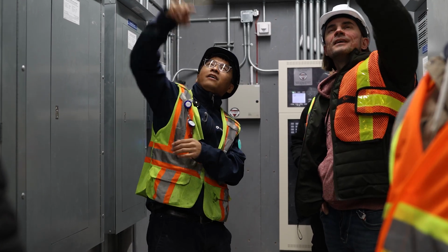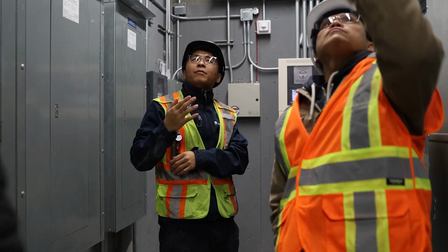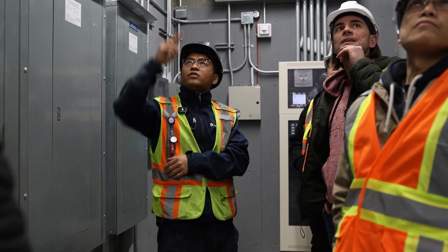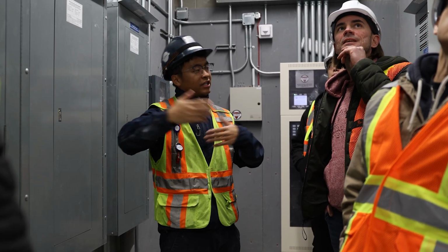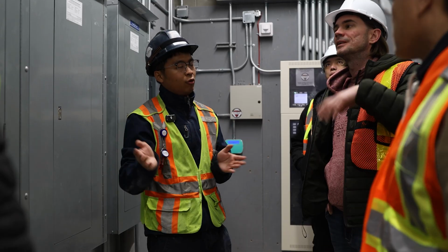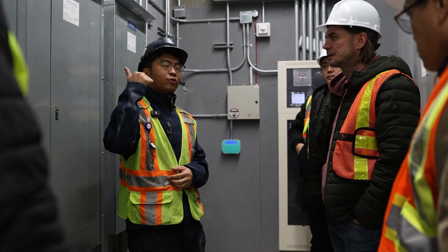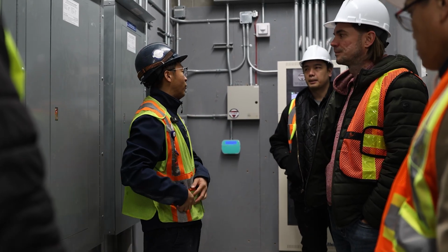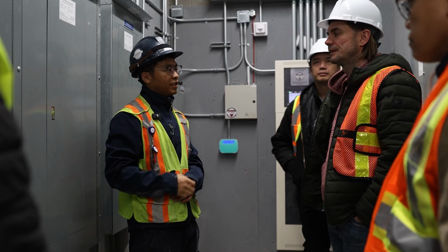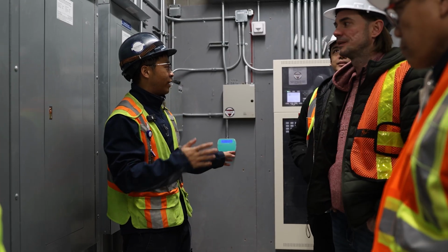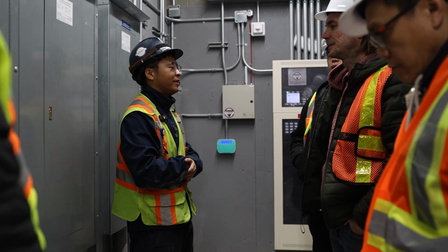So in the summer, it requires cooling, so the heating pipe isolation valve will be closed and the cooling side will open. And once we go to the BMS and look at the graphic, we will go into detail on the sequence of operation. Right now I'm just showing you the location pretty much.